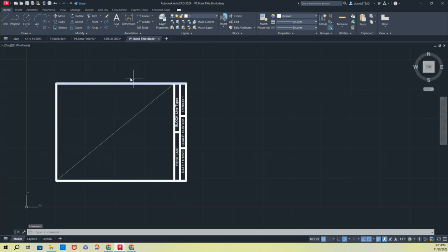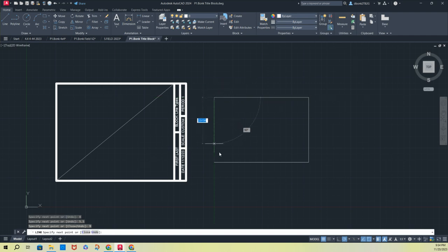Okay, so go click on line, start to draw a horizontal line down here anywhere to the right. Hit 8 on the keyboard and enter. It's going to make an 8-inch line, snap it there. You're going to go vertically, get that green dotted line, you're going to type in 5.5, enter. Back to the left, type in 8, enter, and downward again. And you just get that green box and click, and so you make sure that those points are connected. Hit the escape key and it's going to stop trying to draw any more lines for you,